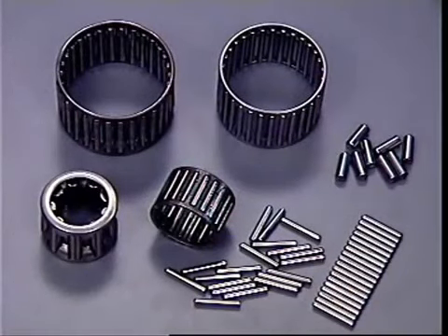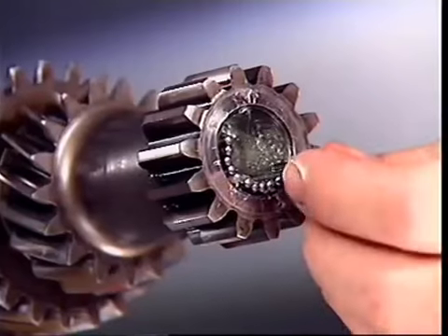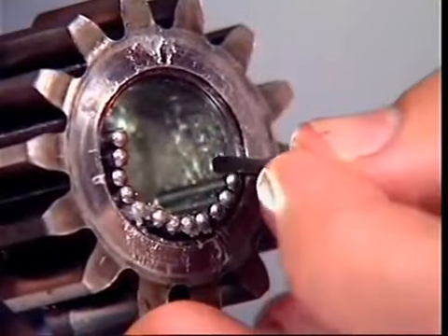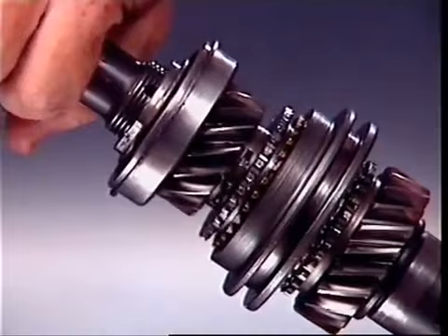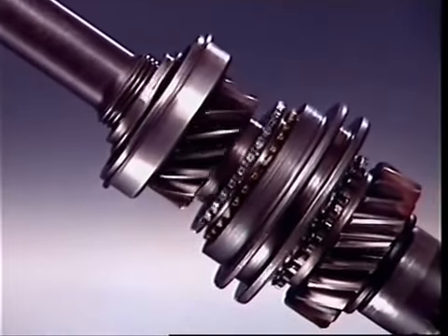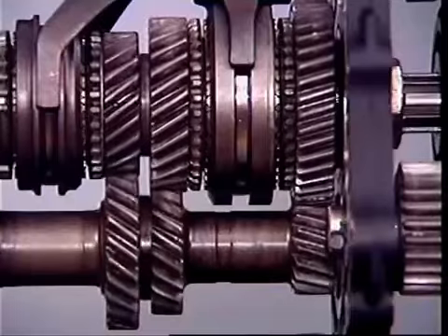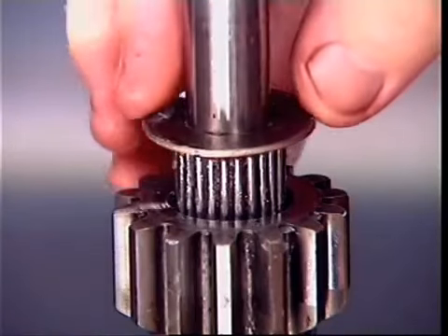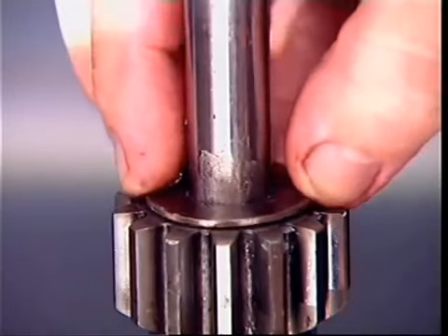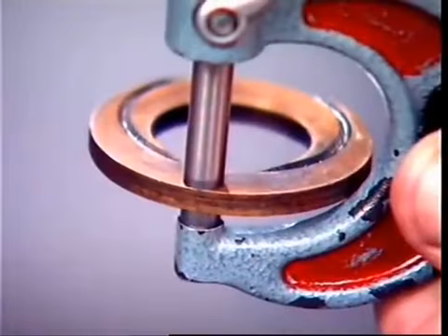Roller bearings are common where loads are purely radial. Needle roller bearings can be caged or as a loose number, assembled to operate directly on a hardened gear or shaft. Typical applications are the spigot on the front of the main shaft, supported in the rear of the input shaft, and in some cases on the countershaft, and the freely rotating gears on the main shaft. Separate thrust washers can retain them and cater for thrust loads. They are often a selective thickness to allow for end float adjustment.